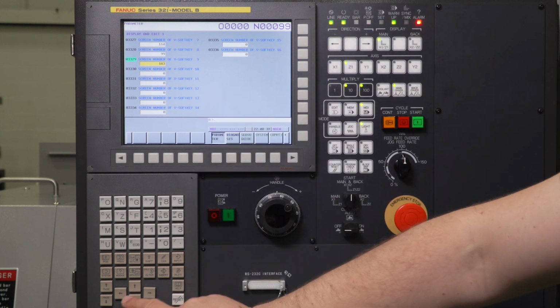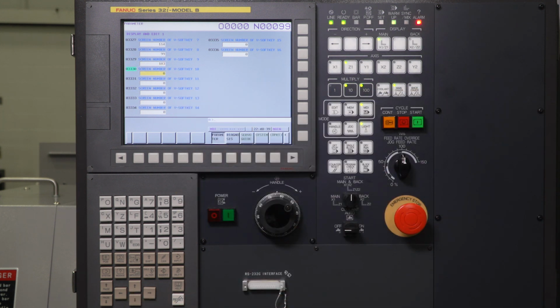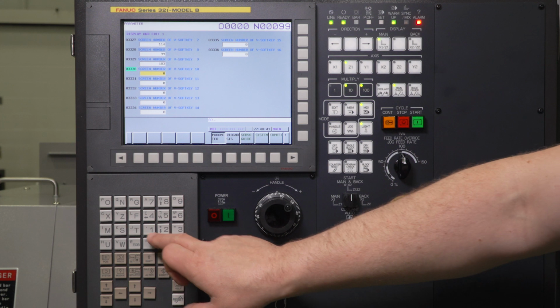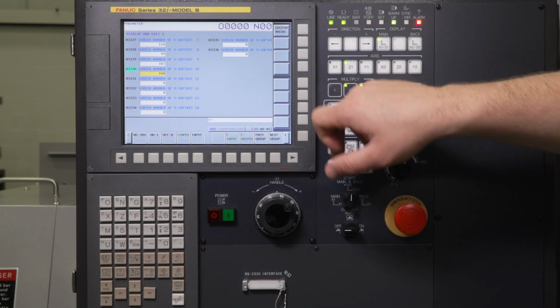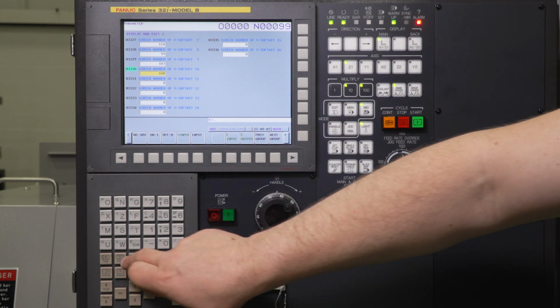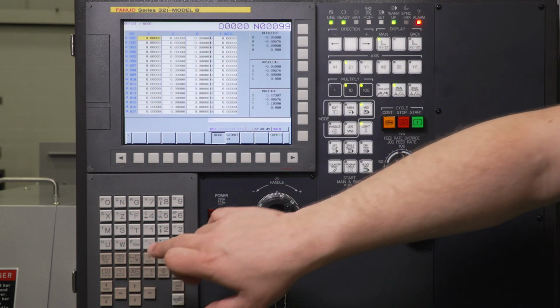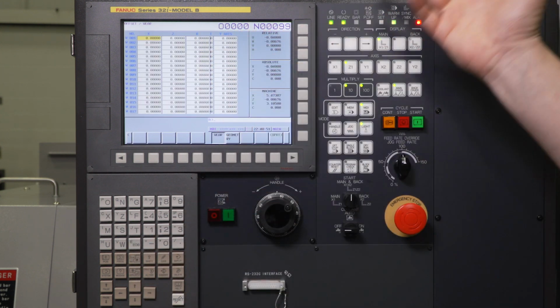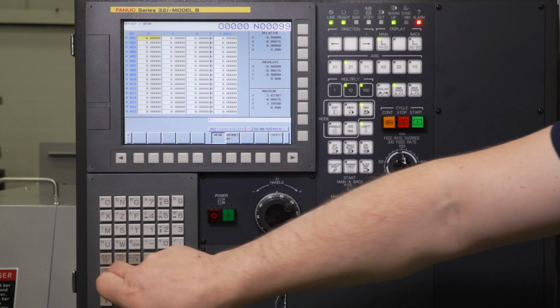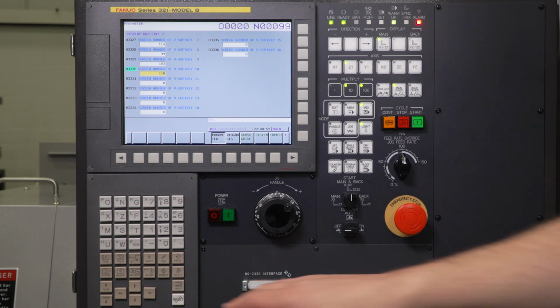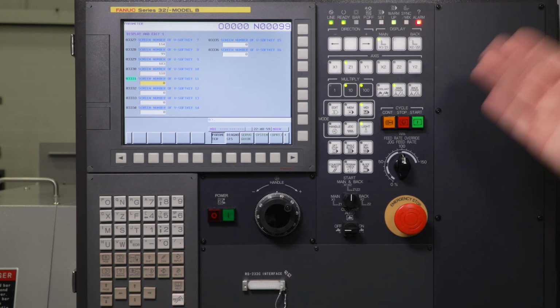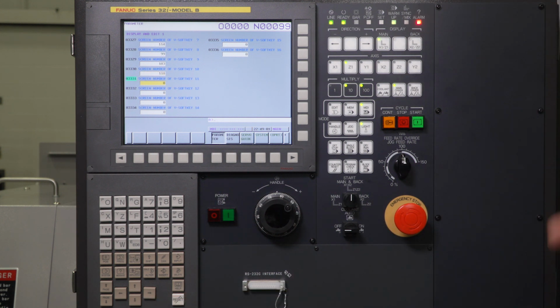So 3330 is our next one. That's going to be our y-axis offsets. We're going to make that a 118 input. And now that's going to be our y-axis offsets, which on this control are actually on the same screen here. So that one actually does not need to be used. You can actually make this a different option if you'd like. Some machines have a y-axis offset on a separate screen. That's going to bring you to that screen.